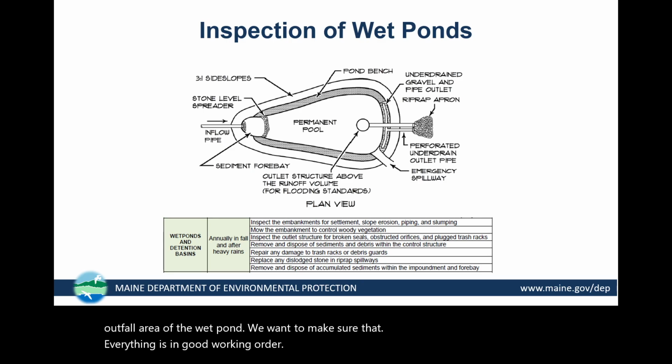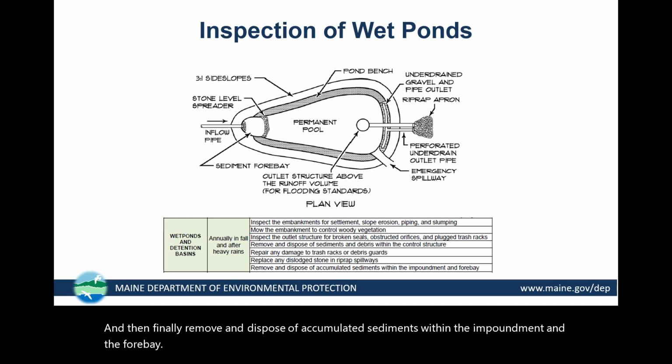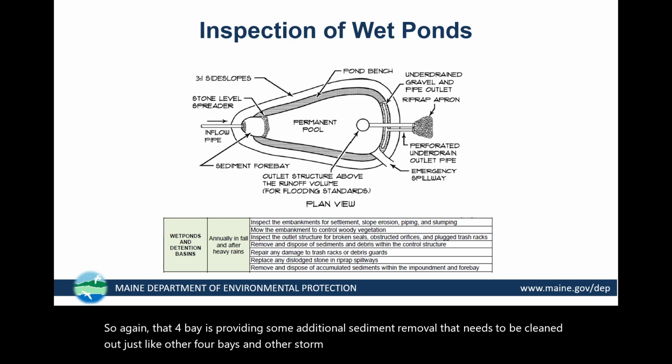And then finally, remove and dispose of accumulated sediments within the impoundment and the forebay. So again, that forebay is providing some additional sediment removal. That needs to be cleaned out, just like other forebays in other stormwater control measures.